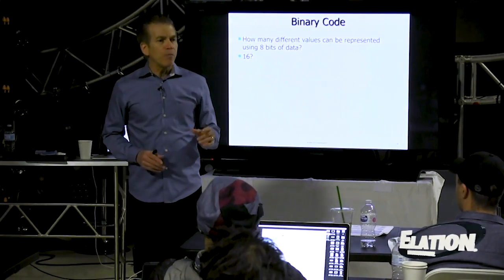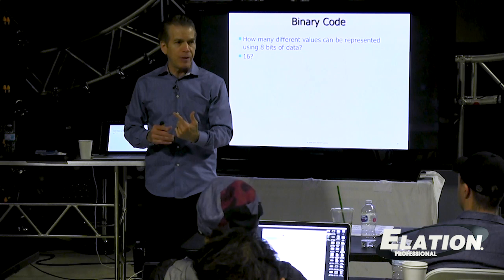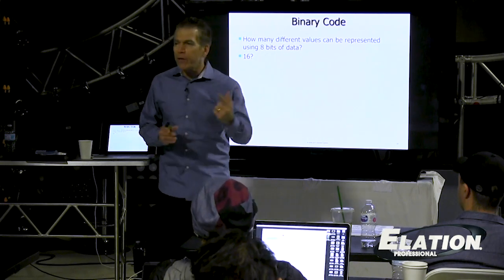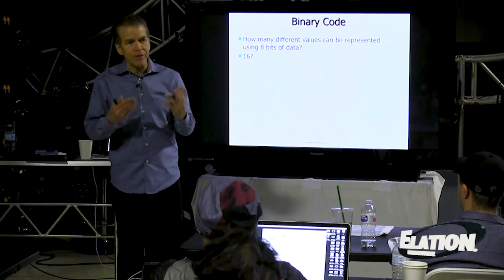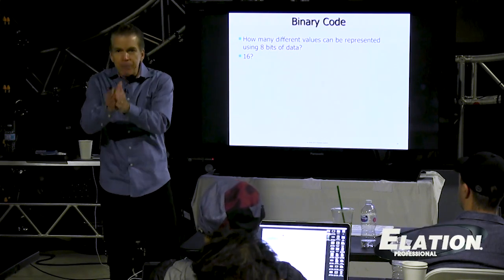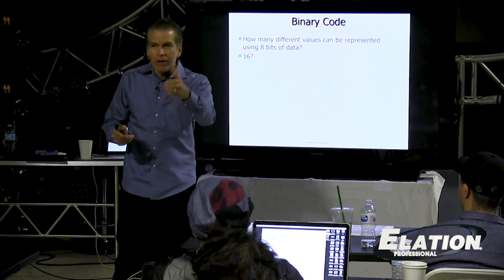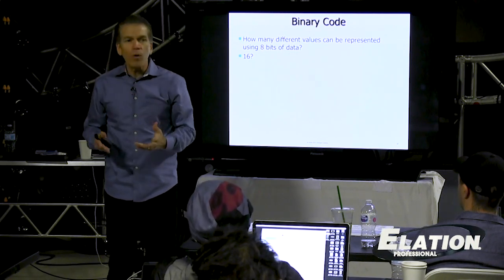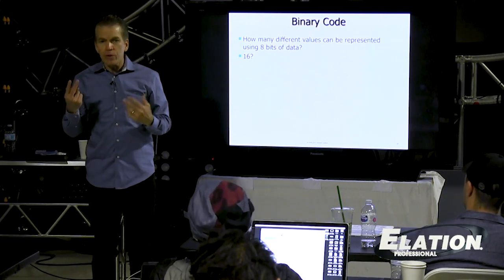On the other hand, most moving lights will pan 540 degrees. So if you have 540 degrees of pan, but you only have 256 levels of control, that's not nearly enough because the steps are going to be too big. So the movement will not be very smooth, it's going to be very steppy. Therefore, for some parameters, like pan, we will use 2 bytes of data to control.